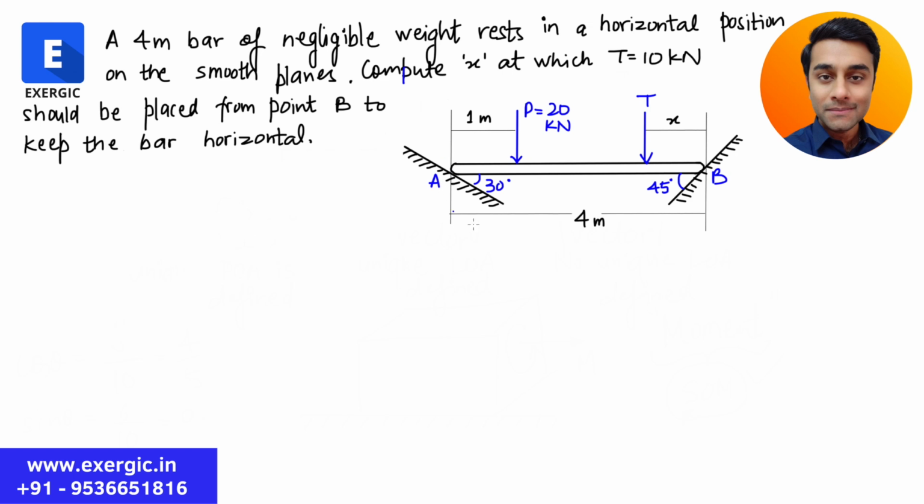So for such a case, when you have a surface and any body in contact with this surface, of whatever shape, at that point you need to firstly draw the common tangent. Now since the surface that we are dealing with is itself straight, this is going to be the common tangent, and then you need to draw a line perpendicular to this, which is going to be the common normal. In the given question, at this point, this is the common tangent, this is the common normal. Similarly here, this is the common tangent, this is the common normal.